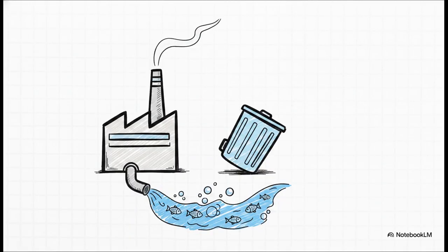But beyond immediate physical safety, power engineers also hold the ultimate responsibility for objective environmental stewardship. They have to constantly monitor plant emissions. How do you reduce CO2? The source points out that the best way is by maximizing overall plant efficiency. Solid waste, the most environmentally sound method, is simply not generating it in the first place. They even monitor the temperature of water released back into nature. Warmer water causes thermal pollution because it can't hold as much dissolved oxygen, which actively harms aquatic ecosystems.